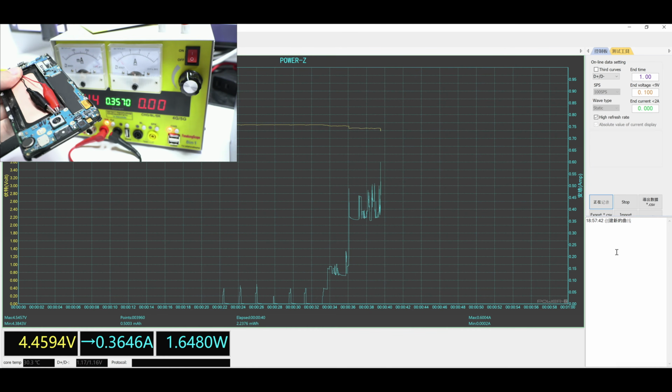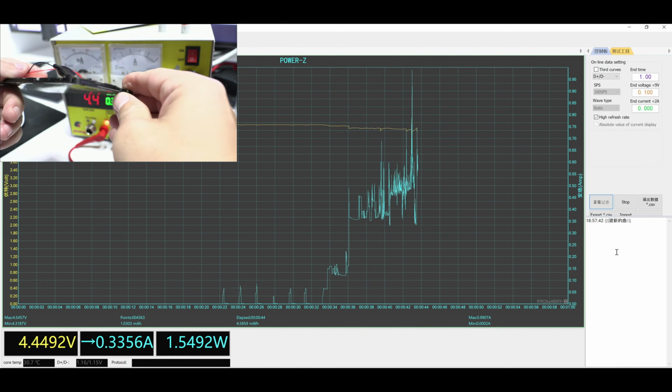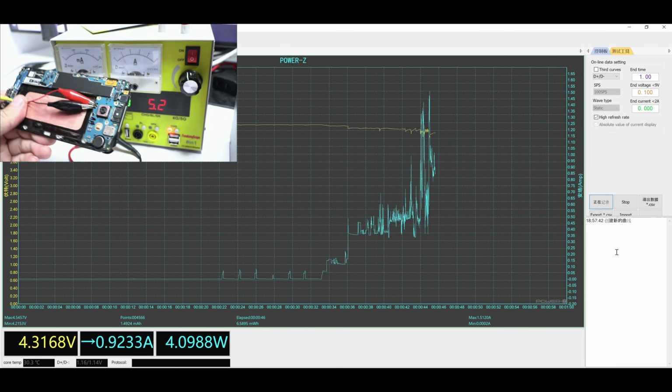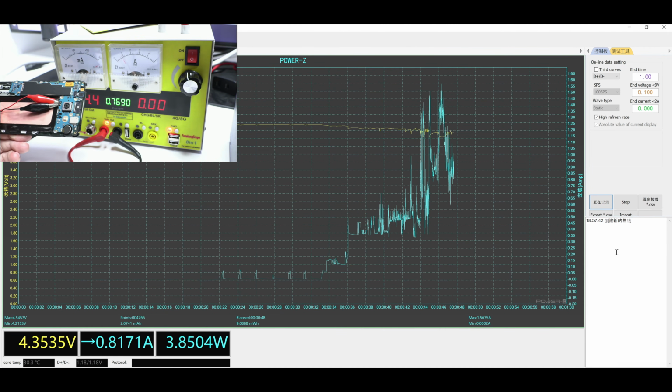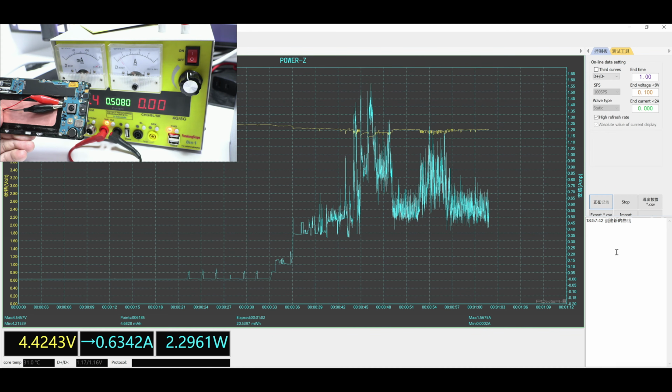By pressing the power button for half a second, the PMIC is acting to deliver a current up to 70 milliamperes. In the next second, the consumption can reach 200 milliamperes without the image appearing on the screen. This means that PMIC, CPU and memory, eMMC, all are working together to perform the power-up, so to speak.